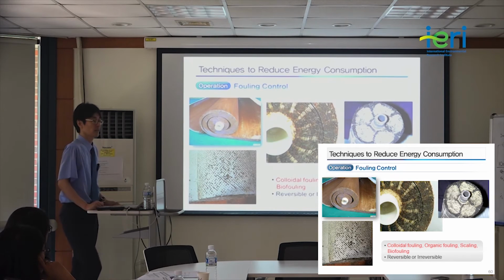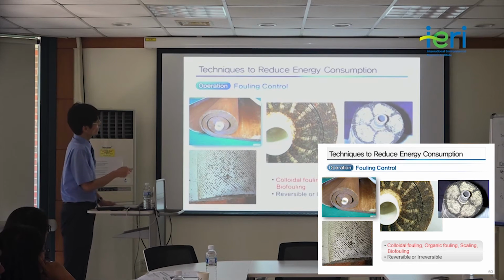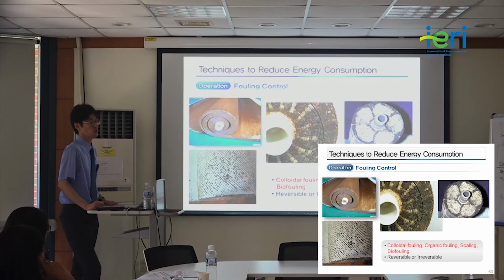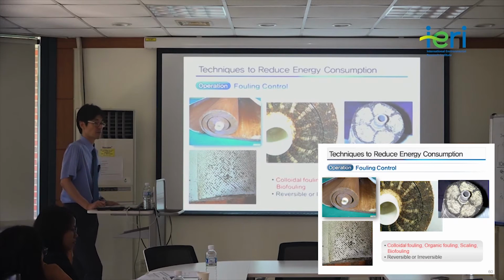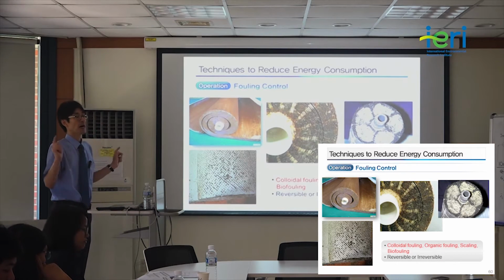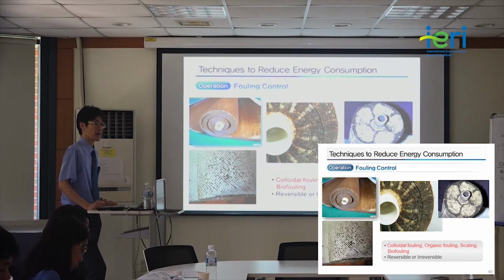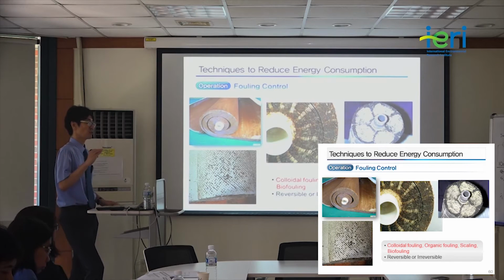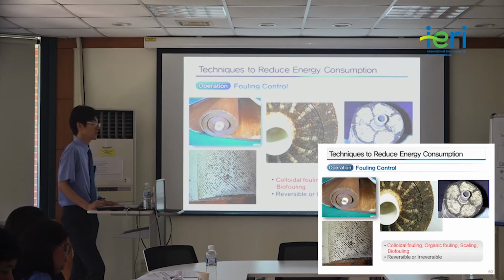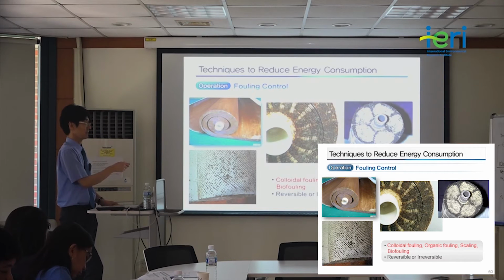So the membrane channel is blocked, and it means that water cannot properly pass through these membrane modules, so a problem happens here. When it happens, you can probably detect that without even taking out the membrane by monitoring the pressure drop from the inlet to the outlet of the membrane vessel. So if this clogging happens, the pressure drop will increase, and then you can easily imagine that this kind of thing is happening.